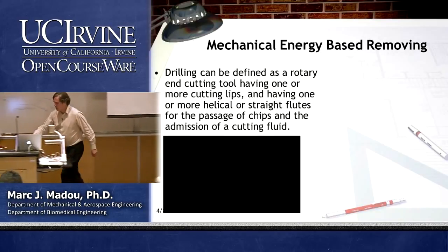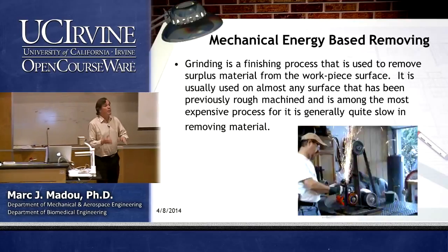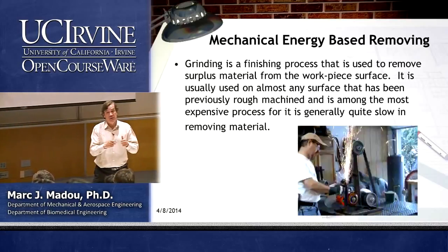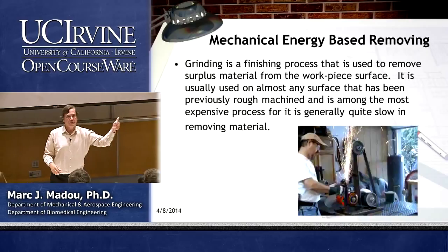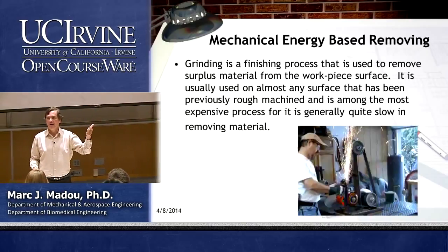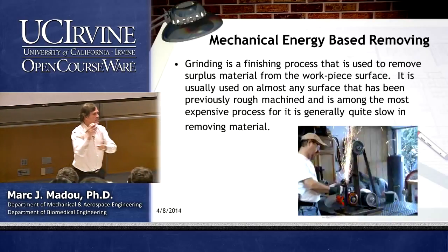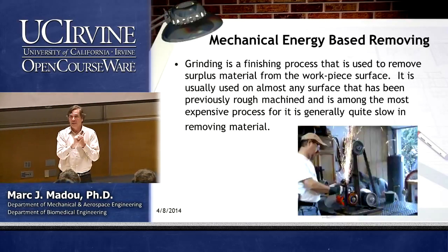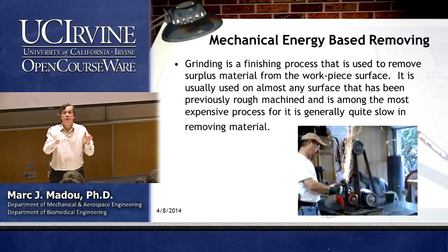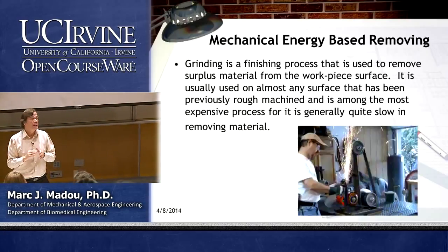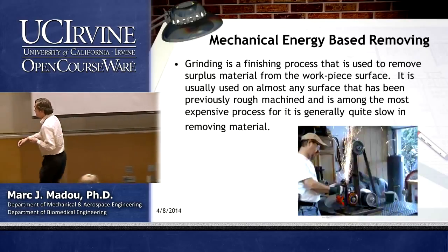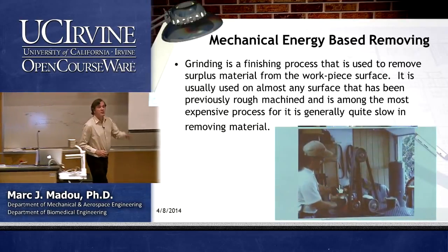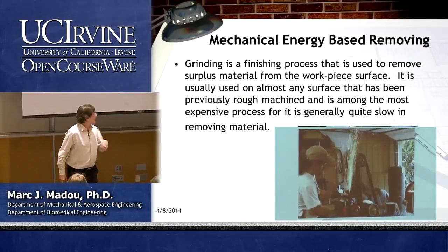Now, grinding was one that I hadn't shown you yet, but probably from what you saw so far, you could completely define what characterizes grinding. So in terms of energy domain, what we apply is obviously mechanical. Is it single point or multi-point? Multi-point. Will it be a more expensive or less expensive technique? More expensive, right? Because it's a primary, secondary, or tertiary technique. Tertiary, right? And we know the cost of a workpiece goes up the more you go to tertiary kind of machining techniques, right? One more thing. Is it subtractive or additive? That's a simple one. Subtractive, obviously, right?